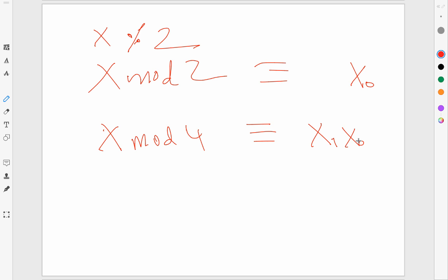Your design would look like the D flip-flops all sharing a common clock, and that common clock is coming from a clock source. It's a periodic signal, and nothing from your data should ever mix with the clock. You should not have any gates between the source of the clock and the clock inputs of the flip-flop. So you should not attempt to AND the clock with this data input or things like that.